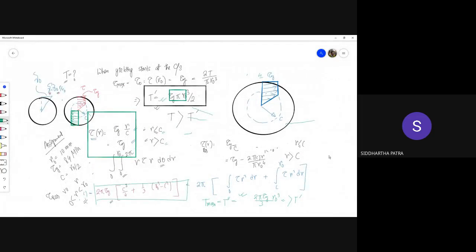In the unloading phase, this is the elastic stress equivalent. In some places it is higher than the elastoplastic stress, and in some places smaller. So this is the elastic equivalent of the applied torque, that is the torque required to cause a certain amount of elastic core.